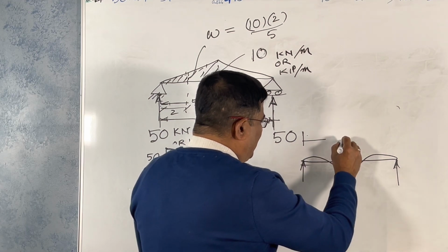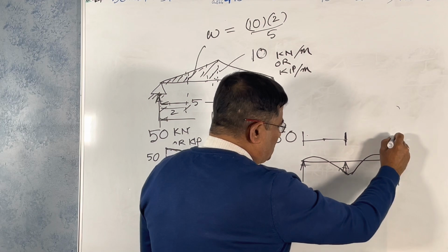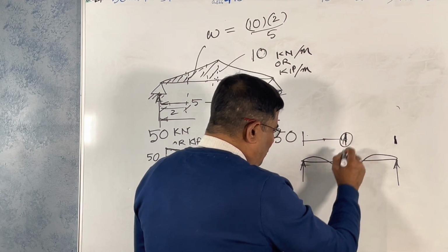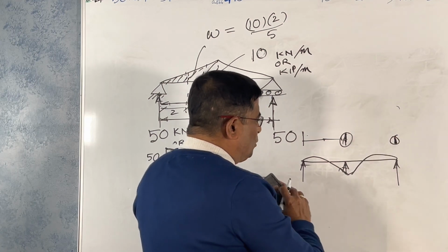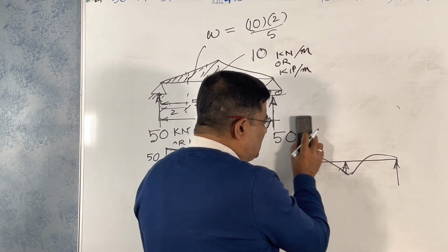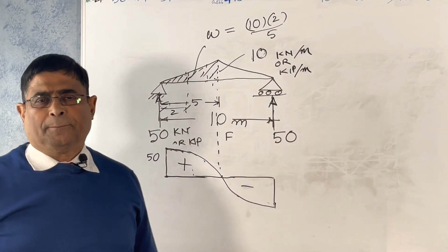I cannot say, it depends on the load. Here the shear force is maximum at the support, because there is a reaction there. So it is not necessarily so for continuous beams. I cannot give you the value unless I solve a problem.